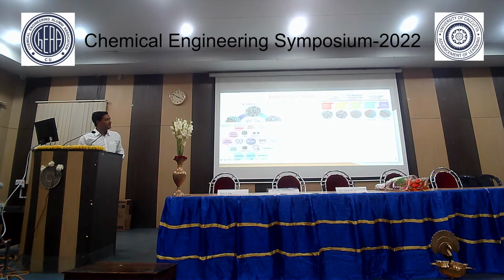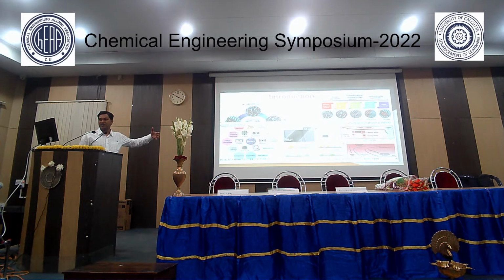And of course, what we are trying to understand is the manufacturing or the preparation process. Here, these are the typical preparation processes which we have seen in the literature. The main drawback of all these processes is that we call it a high entropy alloy, and to manufacture this high entropy alloy you need a lot of energy. That's why you can see this thermal shock method, where you have to put it at a very high temperature, 1600, 1700 Kelvin, and then you are quenching it out. So you need a lot of energy, right?